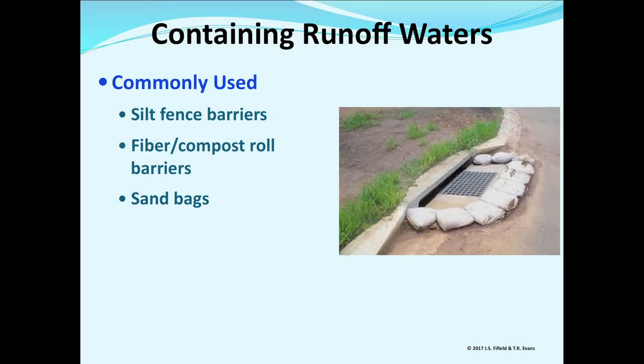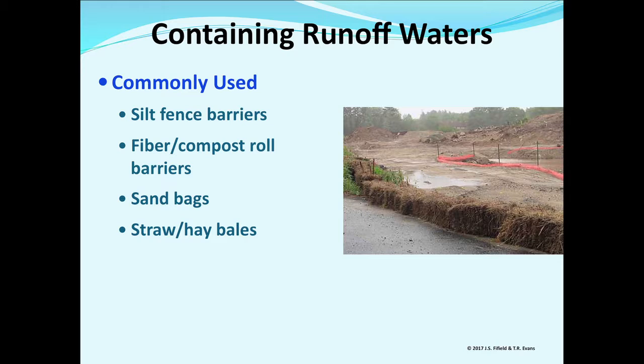California uses sandbags. We don't use sandbags in Colorado because there's something called snow plows that just love to destroy those real fast with the blade. And hopefully none of you ever request to have straw bales on your project. They only work when it doesn't rain. So keep that in mind.